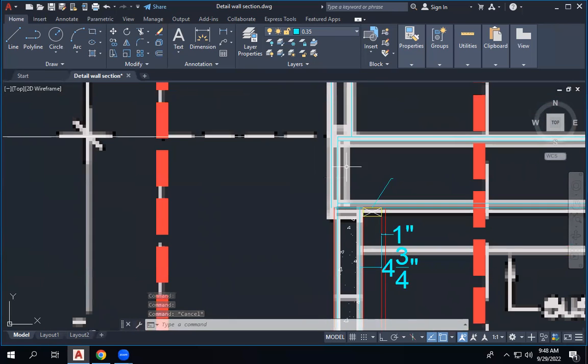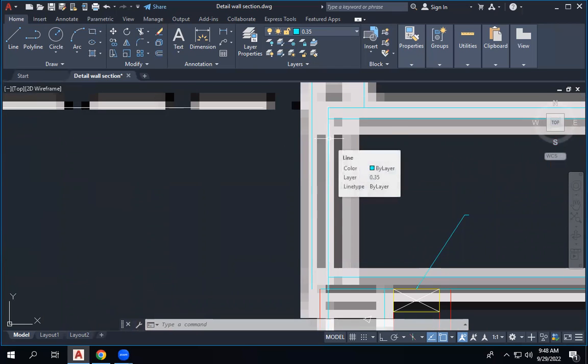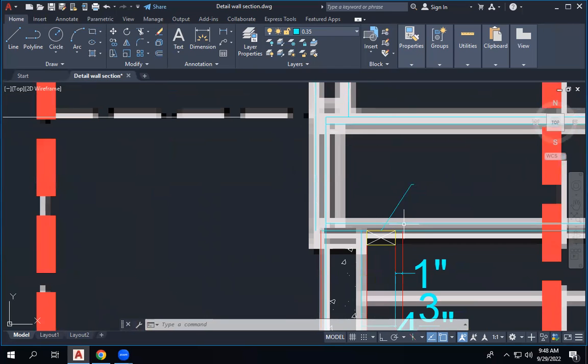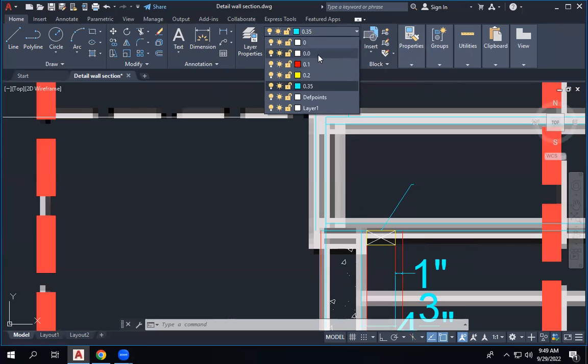So what's the line thickness we use for the truss? What do you think? When we draw the truss, what's the line thickness we should use? Do you have any idea? In sections, we never section the truss. So do you have an idea what to use for the line thickness? The thinnest then? Because you said they usually don't draw it in the sections. Yeah, the thinnest, because it's in the projection. So instead of the 0.35, you can use 0.1 or 0.